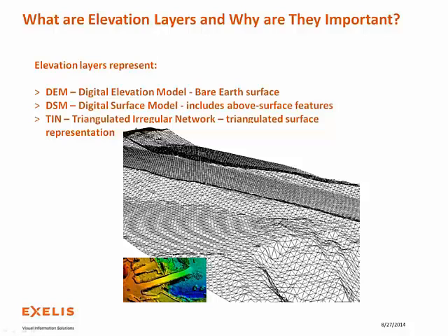Well, there are many different elevation layers that you could use or may have. You'll hear them used interchangeably in the term. So DEM, when I talk about that, I'm talking about a digital elevation model that represents the bare earth surface. There's also a DSM, or a digital surface model, and that includes the above surface features like trees and buildings and anything above the ground.